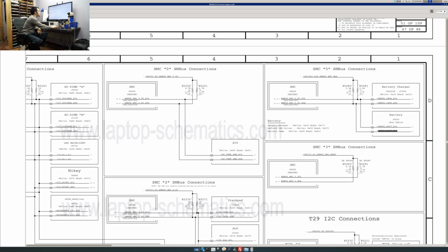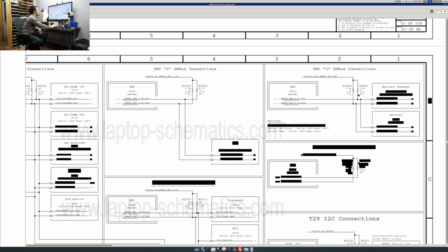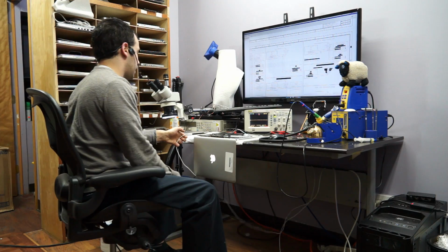That 2 kilo ohms of resistance in that resistor is going to keep everything that happens on the signal side of the resistor from affecting the voltage side of the transistor, the power line side of it. And the easiest way to get this across to you would be to actually show you what it looks like on an oscilloscope. So that's a 3.42 volt line of the system, right?